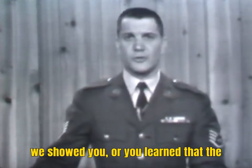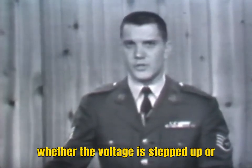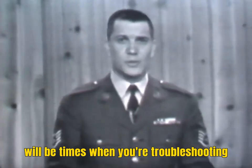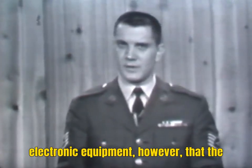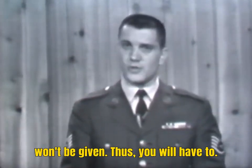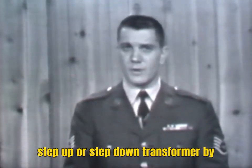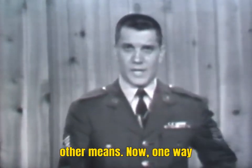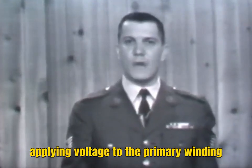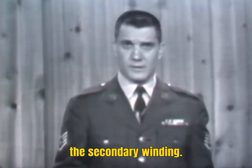Now, earlier you learned that the turns ratio of a transformer determines whether the voltage is stepped up or stepped down, and by what amount. There will be times when you're troubleshooting electronic equipment, however, that the turns ratio of a particular transformer won't be given. Thus, you'll have to determine whether the transformer is a step-up or step-down transformer by other means. One way to readily determine this is simply by applying voltage to the primary winding and then measuring the output voltage of the secondary winding.